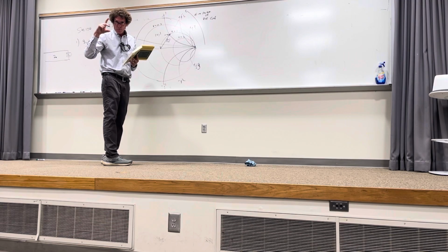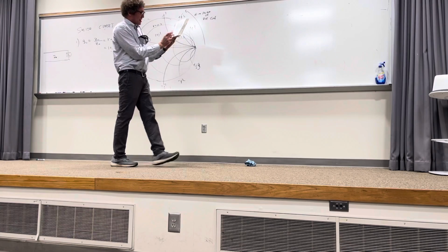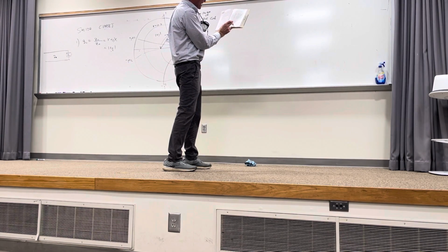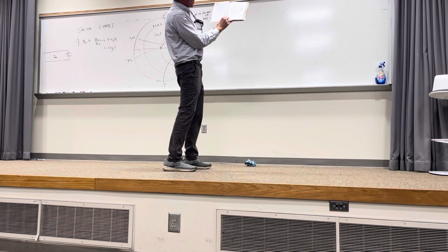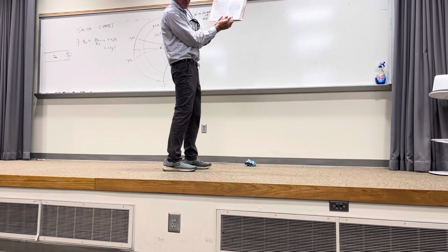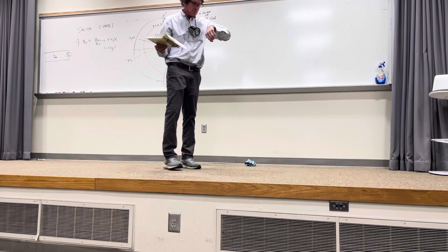The compass is perfect because you have different radiuses. You put it at the bottom there, and you can see when you measure that, the smaller the reflection coefficient, the closer to 0. You always start measuring at this end, and the greatest possible value of reflection coefficient would be 1. You'll see you can measure it right there. You all see that? There's a lot more that we're going to do with the Smith chart, but I want you to appreciate that part.